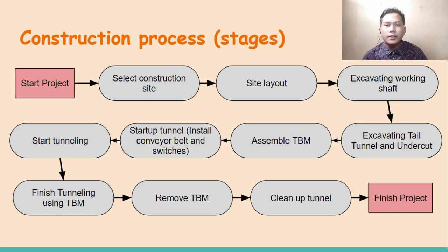As usual, starting the project first. After that, select the location of the construction site. Next, prepare the site layout. And then, excavate working shaft and excavate tear, tunnel, and undercut. After that, assemble TBM, which is tunnel boring machine, and then start the tunneling works. After all the routes being bored, then remove TBM and lastly clean up the tunnel.